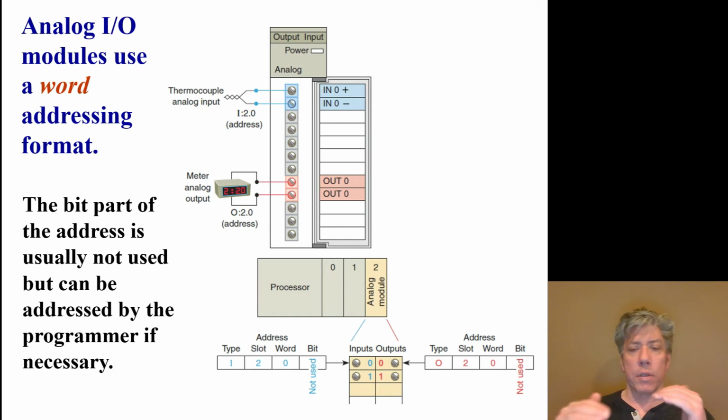You can do a comparison and decide that, once the temperature reaches a certain level, I will or will not do things. For example, in my home heating system, I don't allow my heat pump to turn on unless the temperature is above 40 degrees outside. I allow it to remain on and functional until the temperature drops down to 35 degrees outside, and the temperature has to go back up to 40. So I've got a hysteresis band, if you will, or a dead band there. It would really be a hysteresis band because it's not dead, it can operate. It just operates differently depending on whether the temperature is rising or falling, so that would be hysteresis.